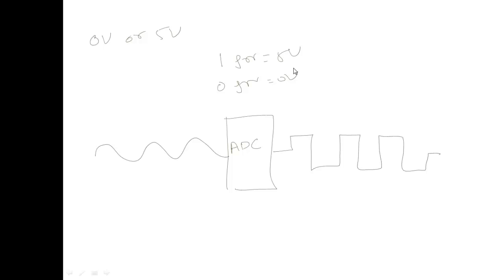For this device in the design, we can use the LM358M, which is a dual operational amplifier. Any general purpose operational amplifier with similar gain and operating voltage can be used, like the LM324M, and we are using the LM358M dual op amp, or you can say operational amplifier. So let's see what the components are and how we make it.